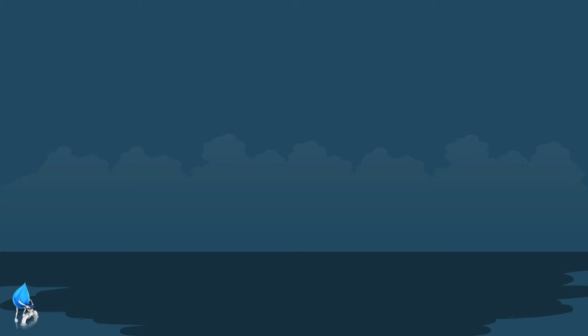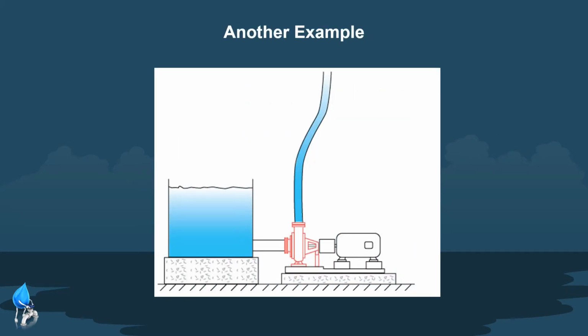To run through another example before we end off this unit, let's have a look at the system below. We will notice that the suction conditions of this example are different, as the suction level of the liquid is well above the inlet to the pump. This is referred to as flooded suction and greatly improves the pump's ability to perform as designed.